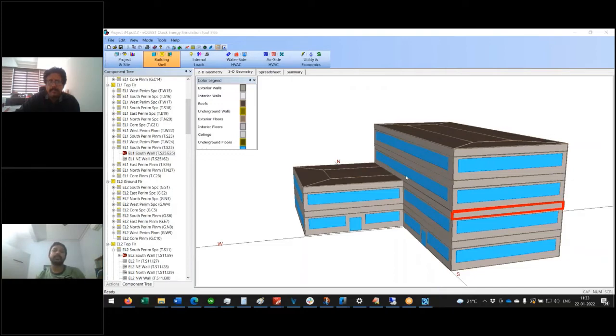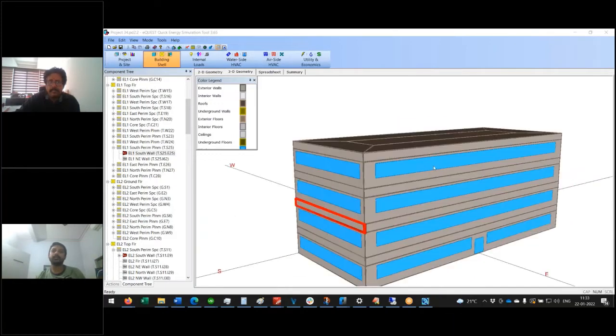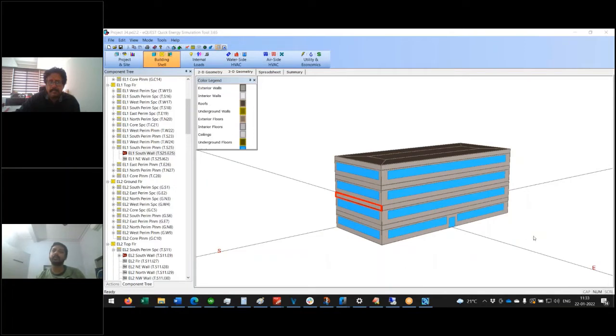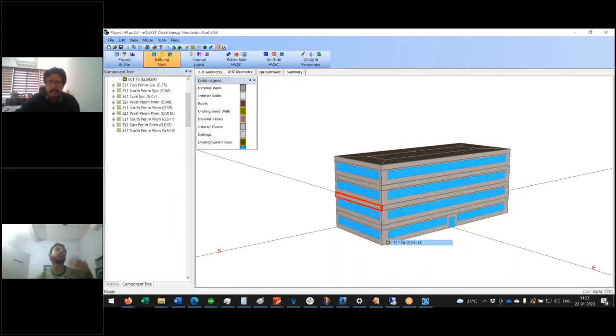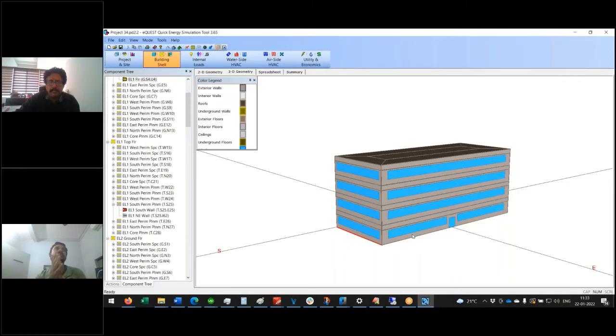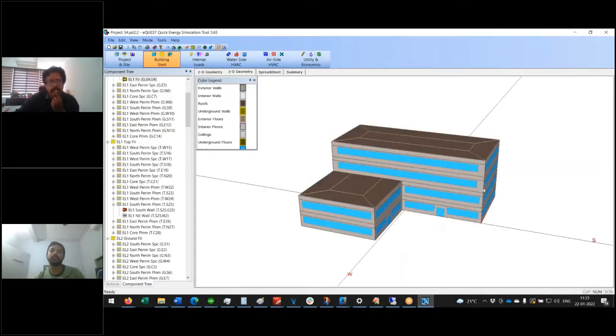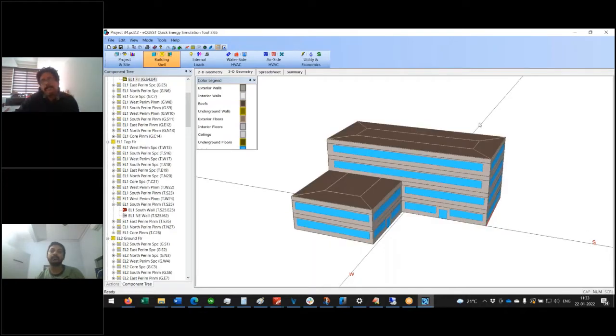So for example, if I just create a building on the side of it, this model, this floor, is not going to consider the shadow. It will always consider it as a standalone. So the same thing goes. It will not calculate the shadow projection in the afternoon. Because you see this wall, this is the south, this is the west.